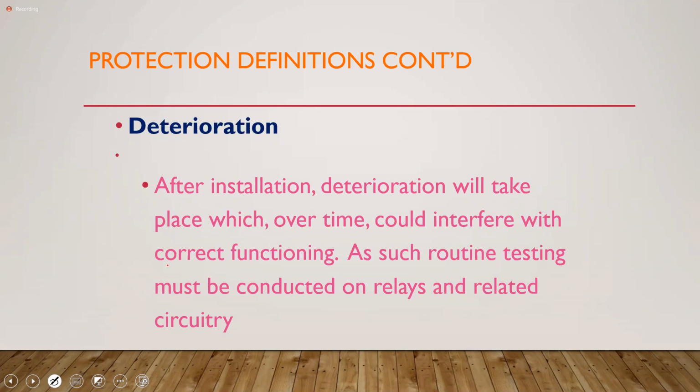There's one other person who was associated with the institution where his responsibility was for the batteries. There are some batteries that are in what we call the relay house. Right? He had that responsibility. There was a fault, but the relays couldn't operate because the batteries were dead. Why? No maintenance. All right.